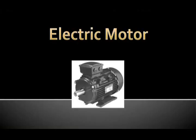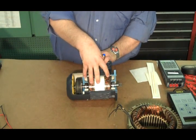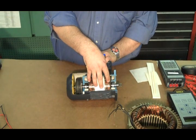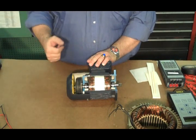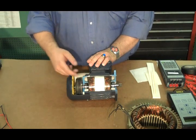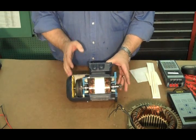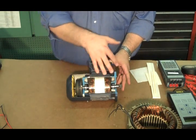In this case, this is a cutaway of an electric motor. Inside the electric motor, we'll have the stator. The stator holds the motor windings. The motor windings are basically what energize the electric machine. Underneath here will be a rotor, and then we have bearings that hold it centered within end shields. The end shields hold everything centered.